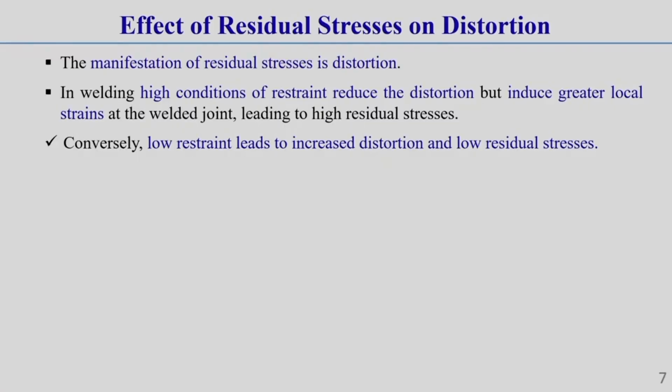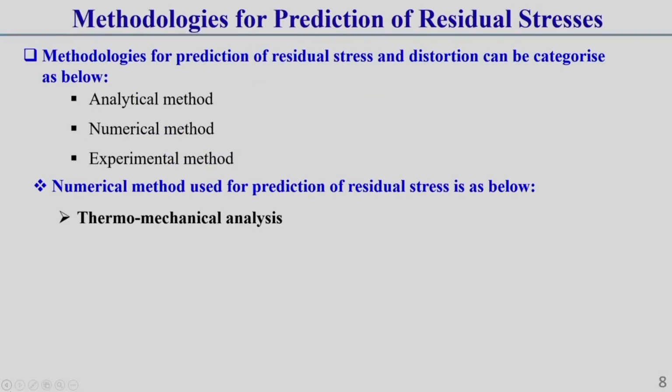Conversely, we can say low restraint tends to increase the distortion, because if there is less restraint, it is free to expand and contract, and then there is a chance of more deformation, but the residual stress will be less.